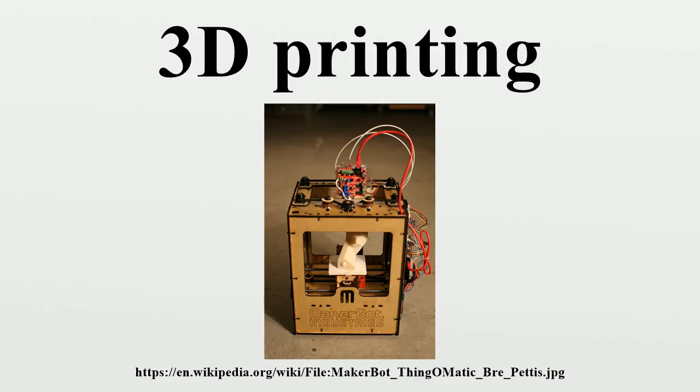These supports must be mechanically removed or dissolved upon completion of the print. All of the commercialized metal 3D printers involve cutting the metal component off of the metal substrate after deposition. A new process for GMAW 3D printing allows for substrate surface modifications to remove aluminum or steel.